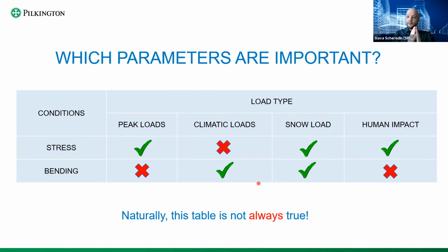So actually, what do you need? For your buildings, you actually need two calculations, not one. First, you need to understand whether your glass will survive. That is the calculation for maximum wind load, climatic load, and everything else combined. Great. But the second calculation, with just the climate load, so just normal outside conditions in winter and summer, will give you an idea how your facade will look in reality.